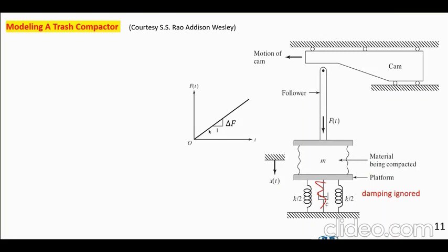It's linearly varying. Incidentally, the slope of this line, force versus time, is the same as the slope of that curve, proportional to it. Let's put it that way. Assuming this is going at a constant speed, this is proportional to it. Now, the response of this problem is ironic, but x of t, this mass, begins to oscillate. As this is moving to the left at a constant speed, this mass begins to oscillate up and down, and the response of it, the displacement of it, is actually like so. In other words, yes, it is following the trend of that line, but it oscillates about that.